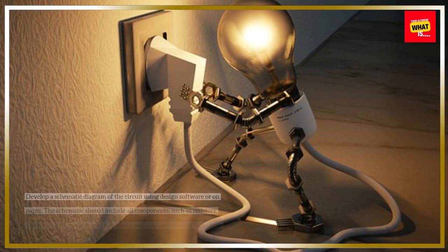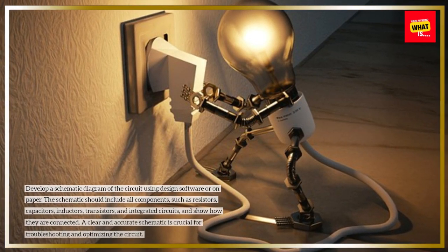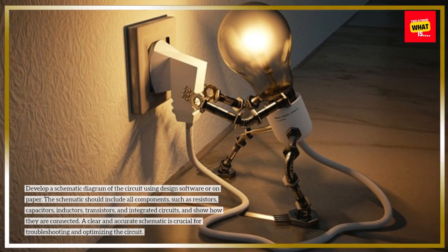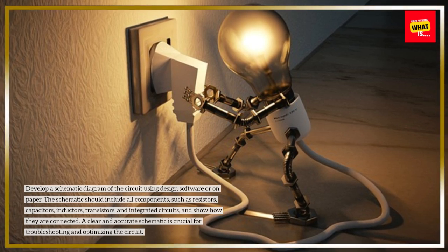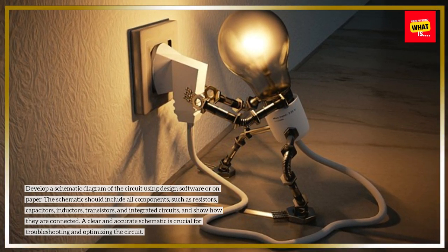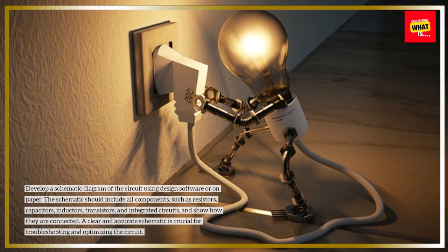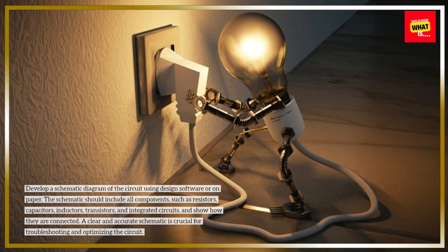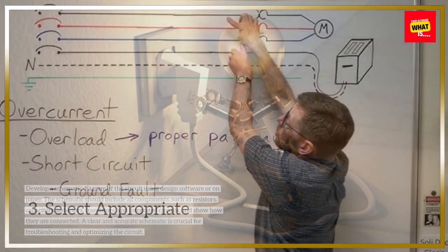Develop a schematic diagram of the circuit using design software or on paper. The schematic should include all components, such as resistors, capacitors, inductors, transistors, and integrated circuits, and show how they are connected. A clear and accurate schematic is crucial for troubleshooting and optimizing the circuit.